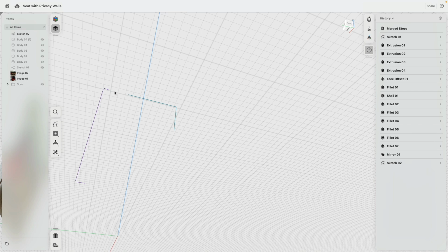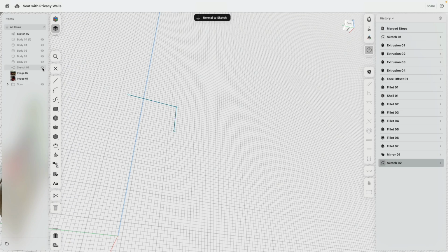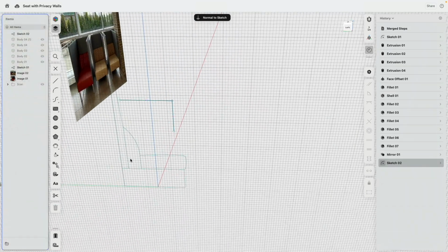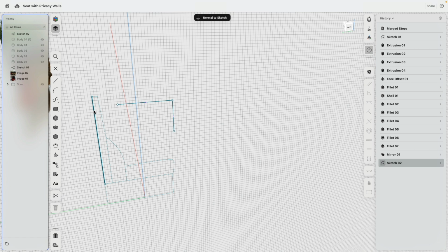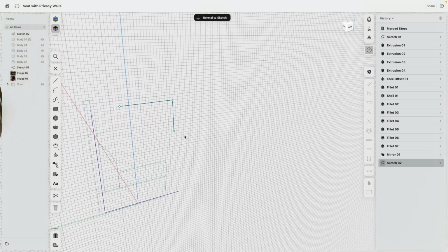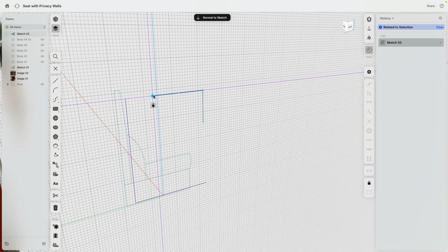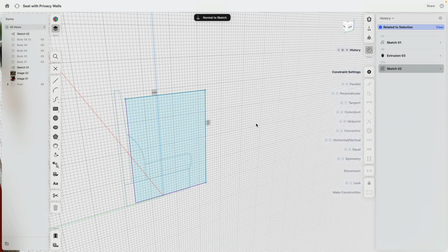Again, because there are always different ways you can do this. I'm going to delete these 3 lines. And I have this original sketch, which you can see is at a different position at the center. But this is now the total height minus the rounded edges. So maybe that's actually better. So from the sketch, I bring this one in. And here, bring this line in. Okay, there. See, this is actually smarter. Because now I can go ahead and say this point glue to there, this point glue to there. These 2 lines, please be horizontal and vertical.